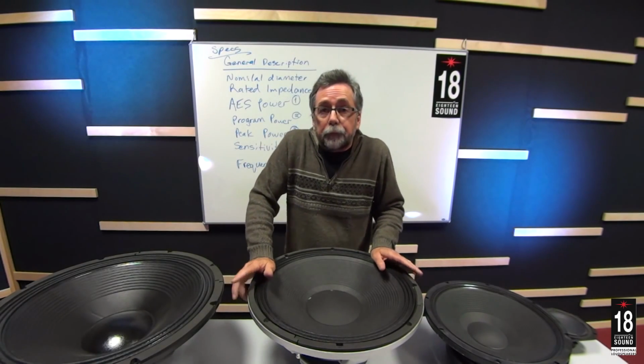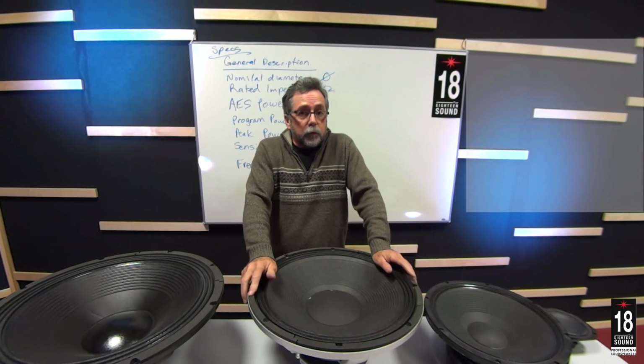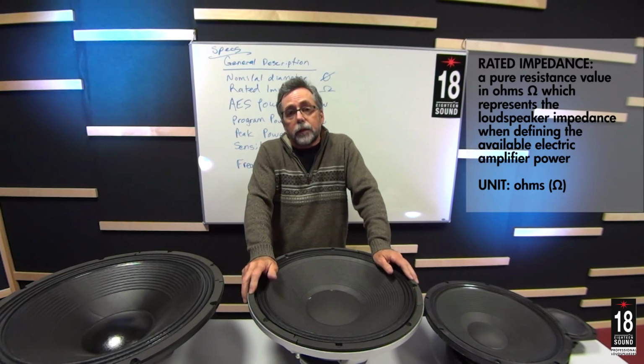The next specification is the rated impedance. Rated impedance is useful so that you can understand which kind of a power amplifier should be coupled. The general rated impedances are 4, 8, and 16 ohms. Sometimes we see 2 ohm loudspeakers, and sometimes even higher than 16.